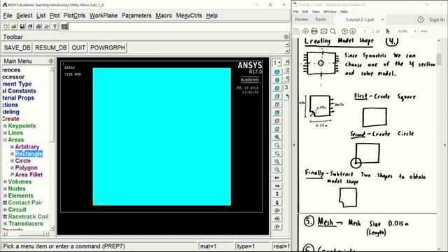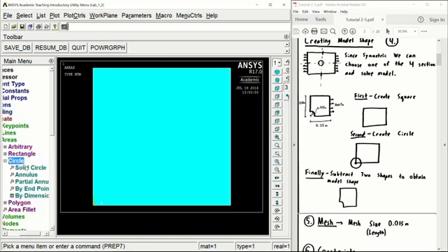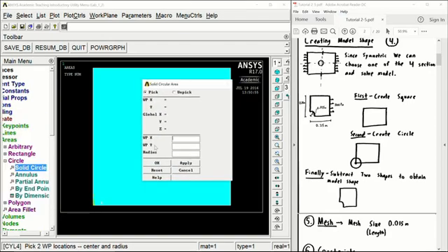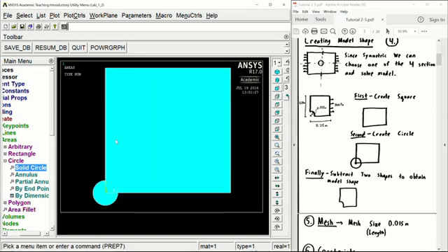And to do that, we're going to close down the rectangles tab here and open up the circle tab and click on solid circle. Same thing here, they ask for a starting coordinate and a radius for a circle. We're going to start it off at the origin once again, and the radius is 0.025 meters. Okay, so now we should have this weird looking shape on our screen.